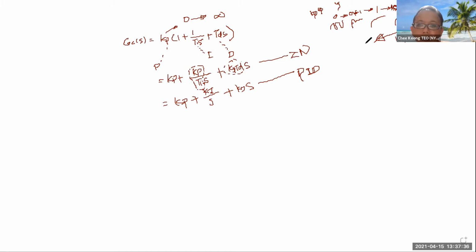At this point, this will be the start of oscillation. As your gain increases, when it hits the underdamped region, that will be the start of oscillation, and it fully oscillates when it is undamped. So increasing your KP will move your damping ratio from overdamped, critically damped, underdamped, and undamped. Of course, at critical to underdamped, it will start oscillation.